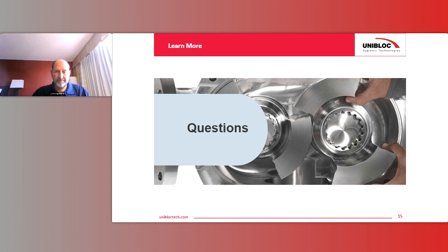Sounds good. For the next question, they asked, how long does a gear lobe AODD pump take to clean? So a rotary lobe pump, if it's not designed for what we call clean out of place, it's for CIP applications. It all depends on the application itself. What's your product you're pumping through? What's what we call the soilage level? How sticky is the product?